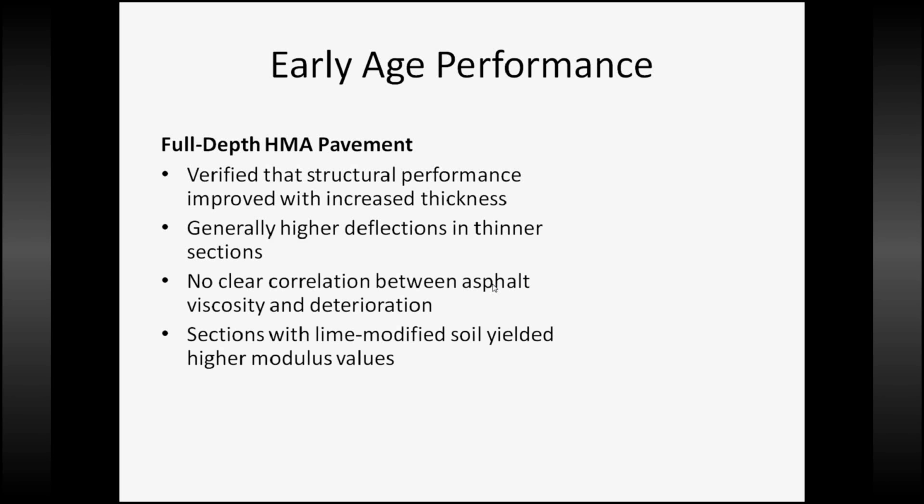We also noticed that the sections with lime-modified soil yielded a higher modulus, and it was noted that during construction, sections with lime-modified soil provided a better construction platform. And we also noticed that the under drains did not show any tangible benefits. We used tipping buckets to evaluate the effectiveness of these under drains, and the results were pretty inconclusive.